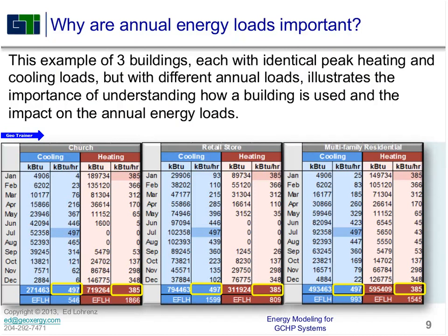And that's why you can get yourself into trouble if you're using standard rules of thumb like that, because the size of the ground loop is going to differ quite a bit depending on how much each of those systems is going to run over the year. In other words, how much energy you're shoving into the ground or how much energy you're pulling out of it.